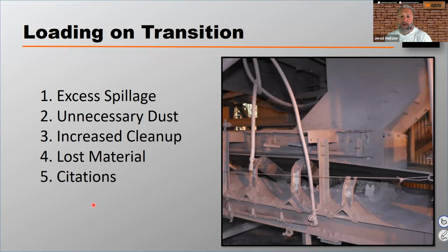So when you design or build or upgrade a conveyor, and don't take into account that the belt should be fully troughed before you load on it, what you've delivered to the user is a conveyor belt that's just not going to perform.